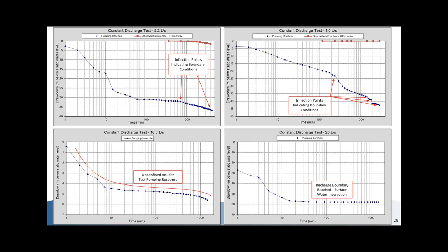we have an unconfined aquifer with a production borehole, we're going to have any rainfall that can pick up potential contaminants and infiltrate down into the aquifer. Those will easily be accessed by the production borehole. Whereas in a confined aquifer, we would have a clay layer or maybe a thick shale layer or something like that that prevents surface contaminants from infiltrating down into the aquifer and impacting whoever is drinking or using that groundwater.